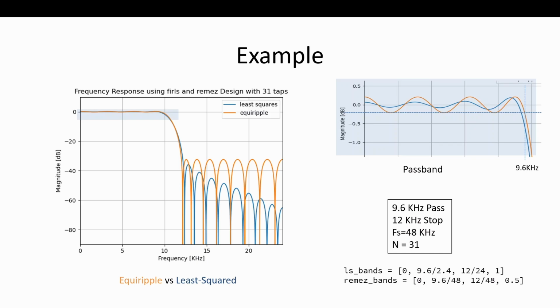And so this is what I'm talking about. If we zoom in, we can yell at it right here. Tisk, tisk, you went off on my boundary in that one little spot, but it's so much lower everywhere else. And it's not getting credit for that, right? So that's least squares versus Parks-McClellan is going to be perfect in this min-max sense. So that's something to be proud of too, right? But it's not what we always need.